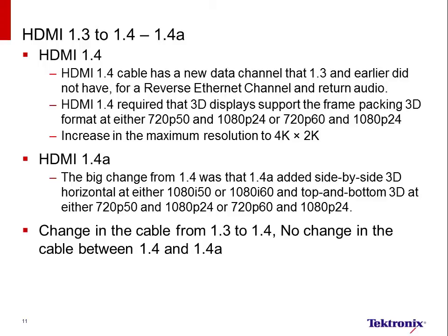There was a change in the cable from 1.3, where we added one more wire so that we could get a differential pair for the reverse Ethernet and return audio channel that 1.3 did not have. There is no physical change in the cable from 1.4 to 1.4a.